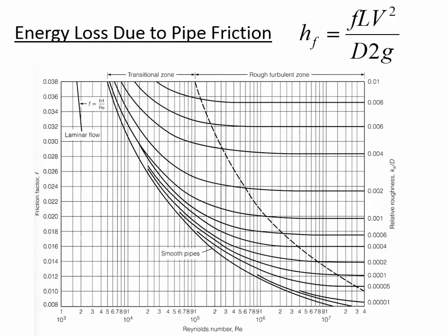And pipes are made out of a lot of different things. You can make pipes out of galvanized iron, it can be stainless steel, it may be cast iron, PVC plastic, HDPE plastic, drawn glass tubing. And so there's a huge range of different materials that water flows through. And each of them has a certain roughness. Now, if I was going to draw a basic sketch of a pipe, maybe it would look like this. You know, it's just two parallel lines and they're each flat.